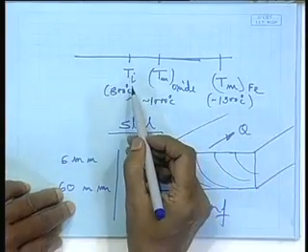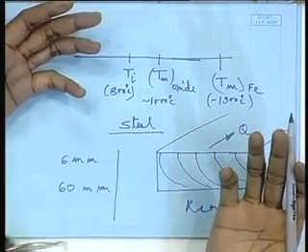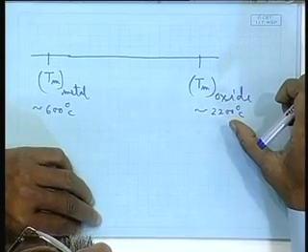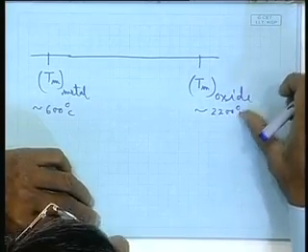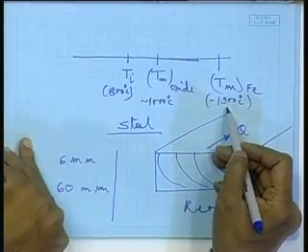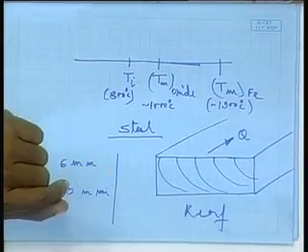because in case of steel, we could ignite the steel, we could burn it, right, and the melting temperature of the oxide was much less, whereas here the melting temperature of oxide is much high. So, I cannot afford to cut it by the so called process of burning, oxidation. So, I will have to go by melting process, means I will not care whether the metal is melting or not, my objective is to melt the oxide straight away in aluminum. I need to have a much higher heat source, because as you can see, for steel I have to attain minimum 1500 degrees centigrade, for aluminum I have to attain 2000 plus degrees centigrade, right.